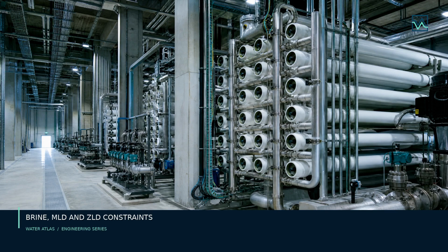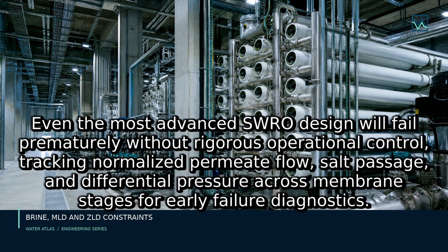boron concentrations. Second, select your intake and pre-treatment technologies based on raw water variability, prioritizing ultrafiltration and robust coagulation where biological loading is high. Third, optimize your high-pressure architecture by pairing variable frequency high-pressure pumps with isobaric energy recovery devices to drive specific energy consumption toward baseline efficiency limits. Fourth, evaluate whether high recovery configurations or brine minimization, including MLD or ZLD, are genuinely required by local environmental regulations or whether well-designed outfalls suffice.